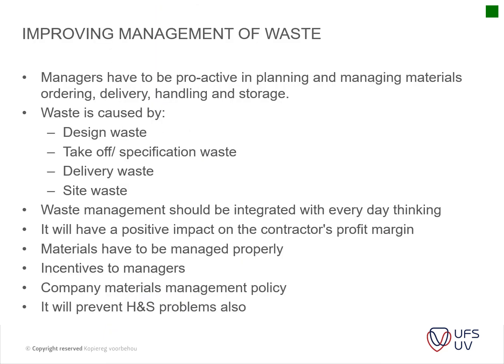Okay, then improving your management of waste. Managers have to be proactive in planning and managing materials ordering, delivery, handling, and storage of it. Waste is caused by design waste, takeoff specification waste, delivery waste, site waste. Waste management should be integrated with everyday thinking. It will have a positive impact on the contractor's profit margin. Materials have to be managed properly. Incentives to managers have to be put into place, and then company materials management policies, etc. It will prevent health and safety problems as well.